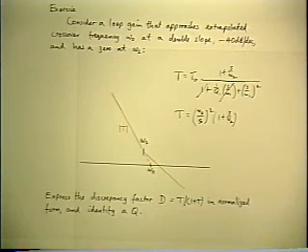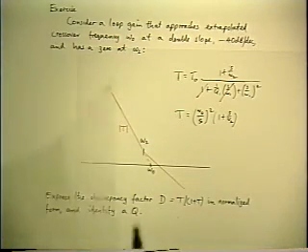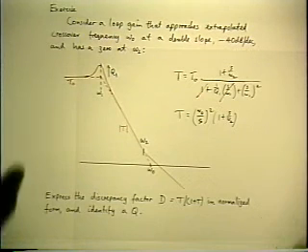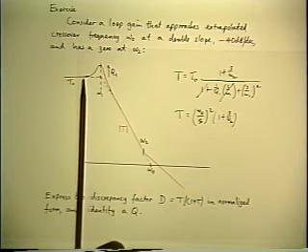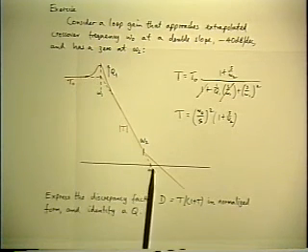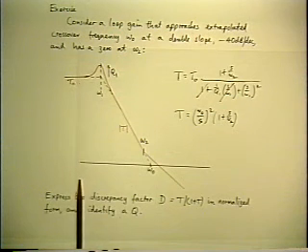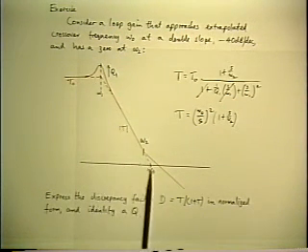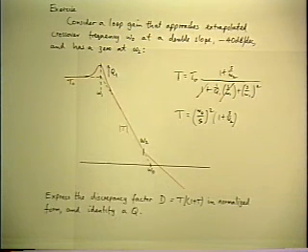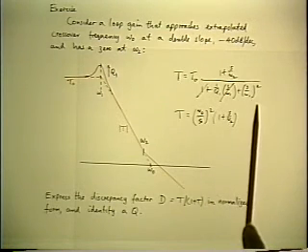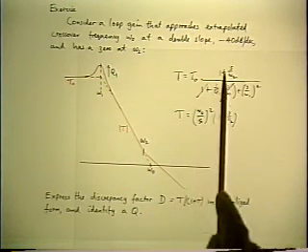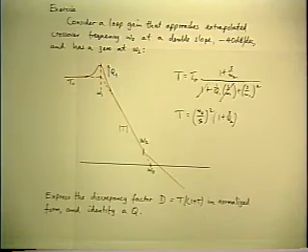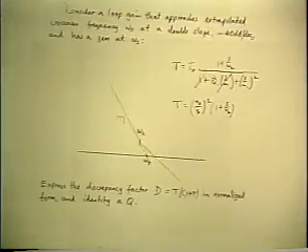That's how we get from one to the other. The gain bandwidth trade-off works here. The ratio of the flat gains between the low frequency value and the axis is T0, and the ratio of the corner frequencies is omega 1 over omega 0 squared, because it's a double slope. And if you make that substitution, you see, T0 omega 1 squared is equal to omega 0 squared. So that's how you get from one version to the other algebraically. But it's much easier to do it on the graph.